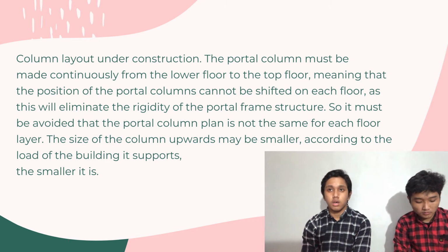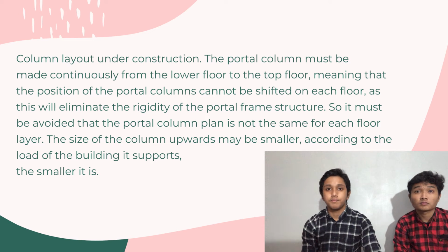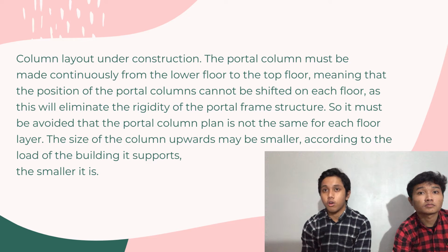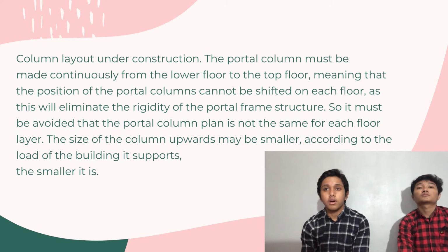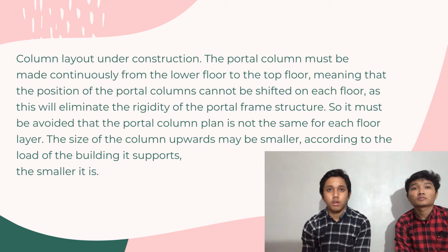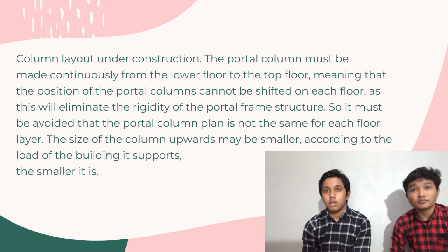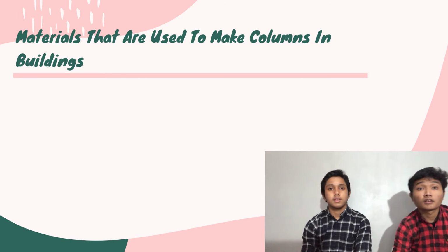So it must be avoided that the portal column plan is not the same for each floor layer. The size of the column upwards may be smaller, according to the load of the building it supports.